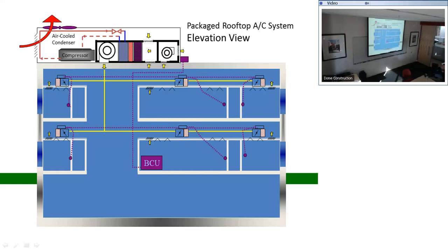That little thermostat right there modulates that damper right there, modulates air. And then we keep it to a minimum. We always want to ventilate the space, so you stop it somewhere. And if I still need to reduce the cooling, that's where I reheat. So I reheat for interior zones. Say this is even interior, but I want to ventilate this. So I'll have a reheat on this, but now I have an exterior, so I'm heating.